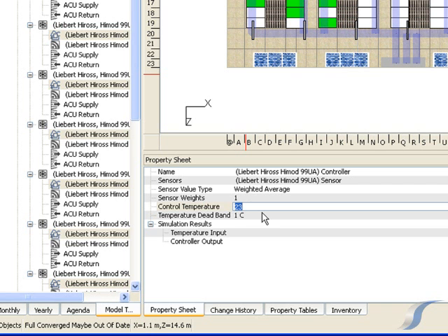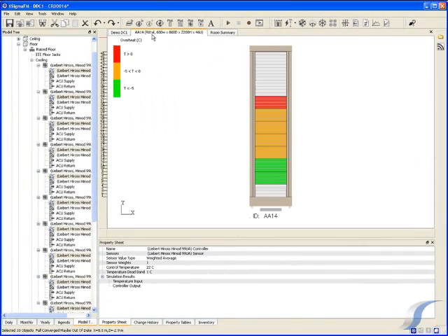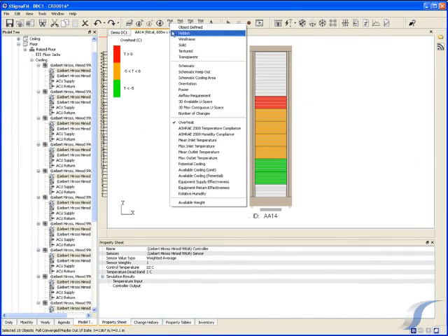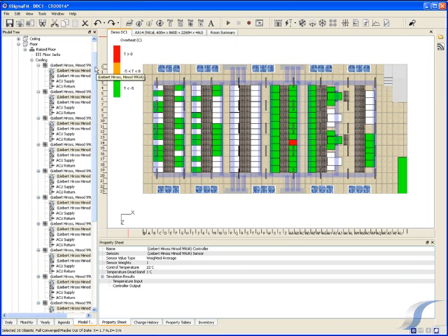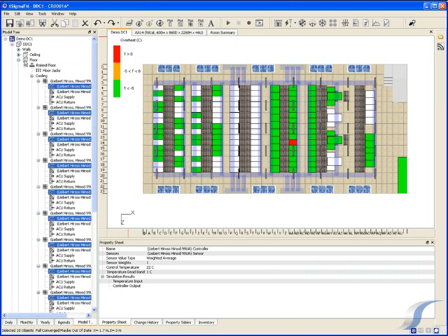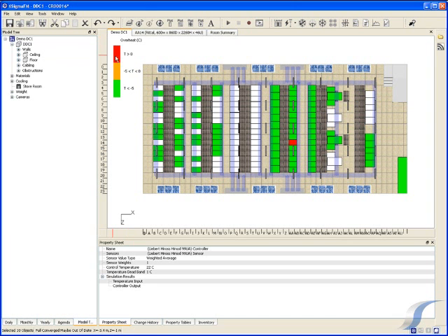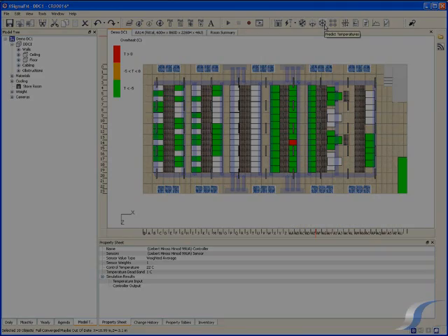Note, however, that a 1 degree reduction won't achieve our 5 degrees safety margin. If we look at standard recommendations from the American Society of Heating, Refrigerating and Air Conditioning Engineers, or ASHRAE, they also suggest that we should be dropping our set points by about 5 degrees. However, just for the sake of this demonstration, let us mimic what happens in real life in many data centers. The set points are reduced by the minimum amount, and the data center is just on the verge of overheating.